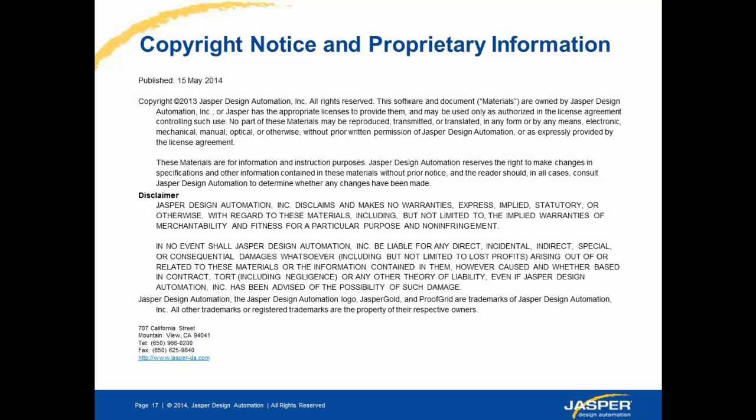Mike Benjamin, I'm a consultant. It seems to me that your definition of property completeness is a bit like line coverage. It's a lower bound. It tells you if there's a bit of your design you hadn't touched at all. It doesn't really tell you if you've tested all the functionality. So it's not clear to me what value it adds, as most of the formal we write we don't expect to be totally exhaustive, and it could be checked by functional coverage points. So what heuristic proof is there? You gave some indication that some of your customers have tried this, but how are you trying to validate that it actually adds value in the same way?